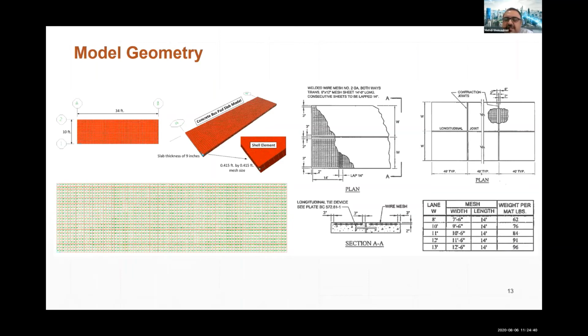We saw in the results that the moment is shown in two directions. That means the slab is performing like a two-way slab.